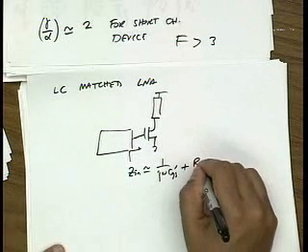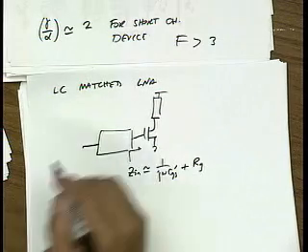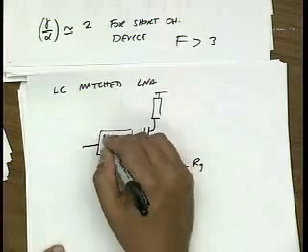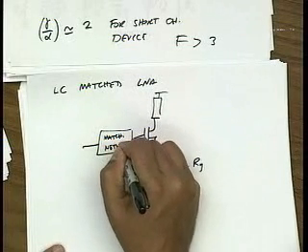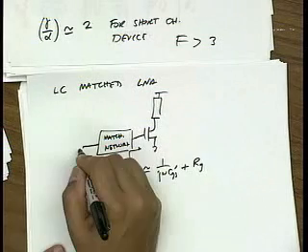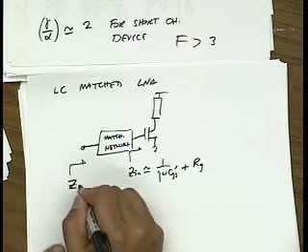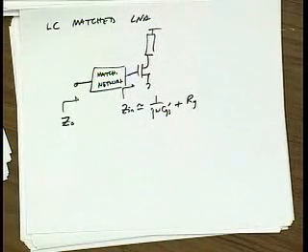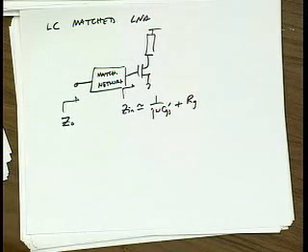Let me put in our gate here as well. I'd like to have a matching network, so this could be a pi matching network, an L matching network, or some arbitrary matching network that transforms this to, or let's just say in this lecture, Z0. Okay. So what are some of the issues with designing this matching network?